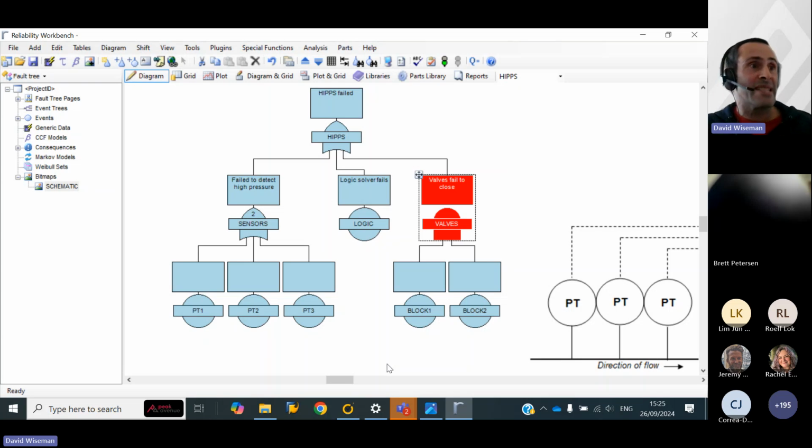Obviously, there's the quantitative bit that you might think of straight away, the probability calculation. But you also have that qualitative analysis where it's possible to determine from the fault tree what combinations of events, if they were to occur together, would result in a dangerous failure of the system. What combinations of these events would lead to that problem? You can in fact do this analysis of a fault tree without any numerical data at all. And that on its own can be useful even before you start entering numbers into a fault tree. So maybe we'll do a little of that first.